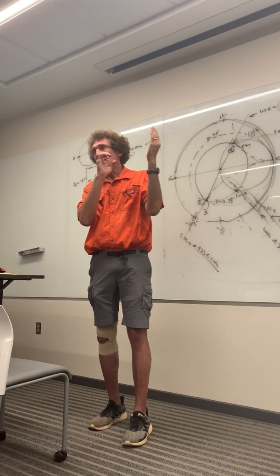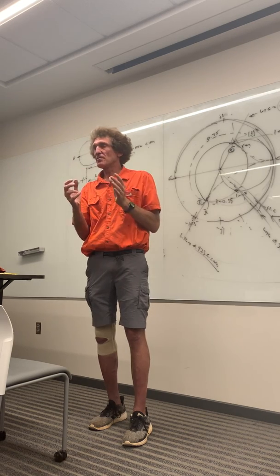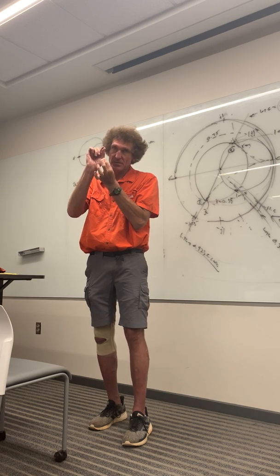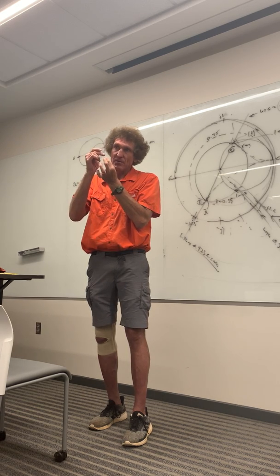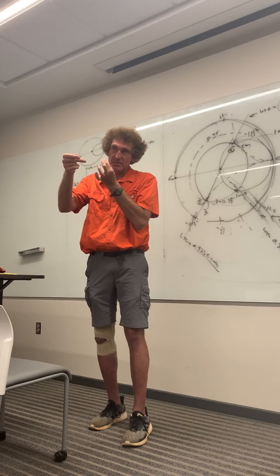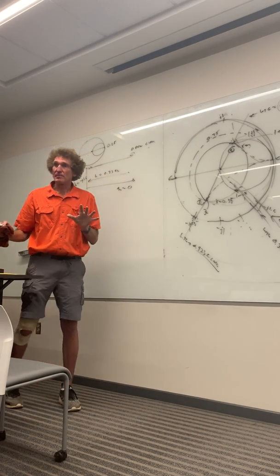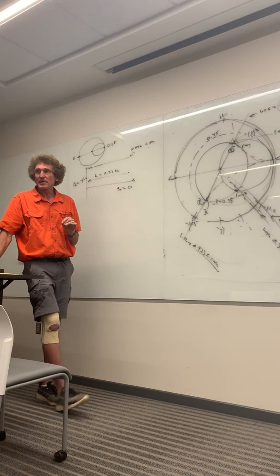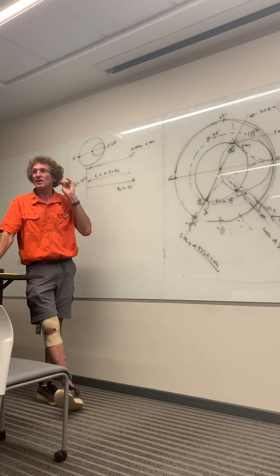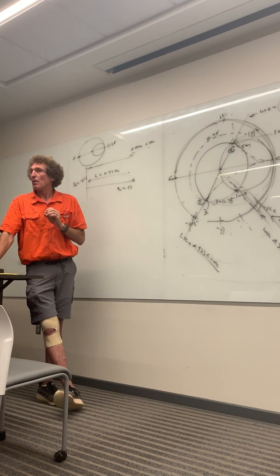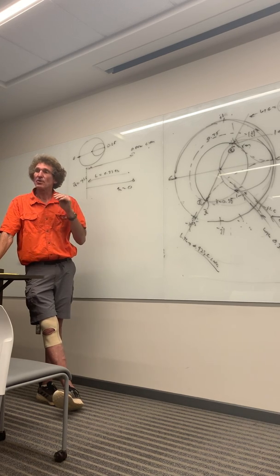where the charge is. Well, when you have a lot of devices electrically jammed in an area, anytime you have a plus to minus potential difference, that field can actually influence the circuits next to it, all right? And remember, that thing's oscillating at a high frequency, and it can corrupt it. That's what I'm saying. You're gonna hear about things called intermodulation distortion, and you're gonna hear about interharmonic distortion, you're gonna hear about all sorts of things, but one thing you're gonna also hear about is something called crosstalk.